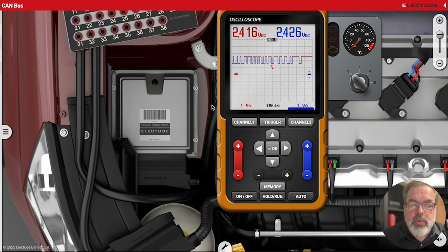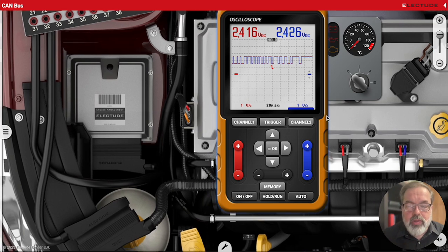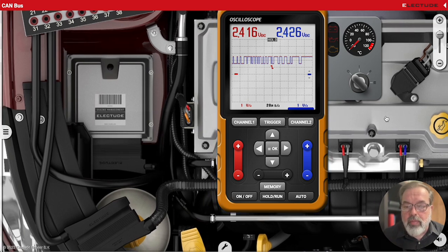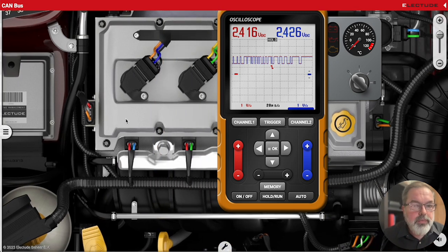That's why I think it's really important to line up your 0 lines so you can more easily distinguish which one of the 2 signals you are missing if there's an open. And you're going to encounter open circuits more often than short circuits, just due to most faults, the wires will be broken or something like that. Shorts can happen too. This particular fault is an open.